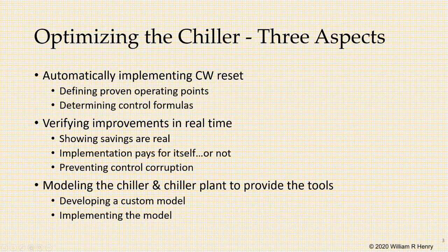Of the various strategies for optimizing a chiller, the biggest bang for your buck is achieved by implementing condenser water reset. For instance, Siemens demand flow pumping, while it includes an expensive control scheme for the entire chilled water system, careful analysis shows that it depends on condenser water reset of the chiller for the majority of achieved saving. This goes for the Johnson Controls optimum energy method as well.